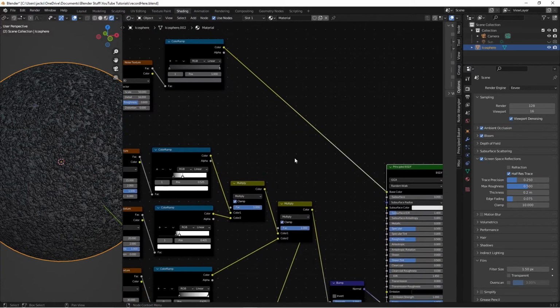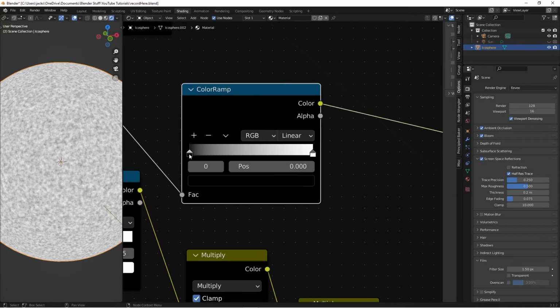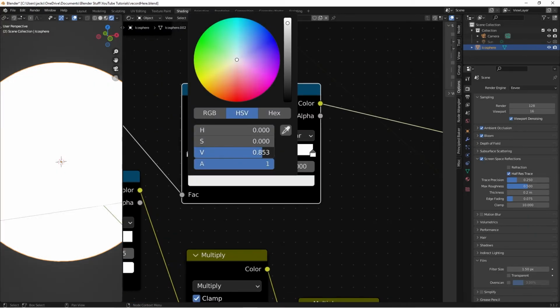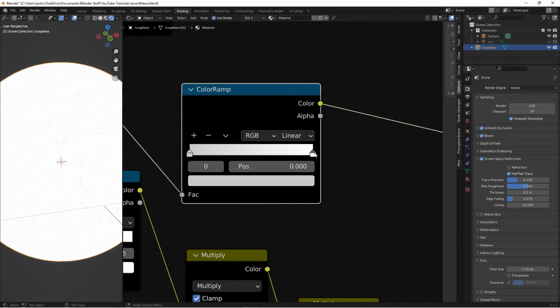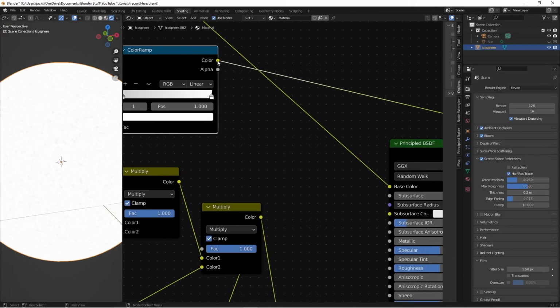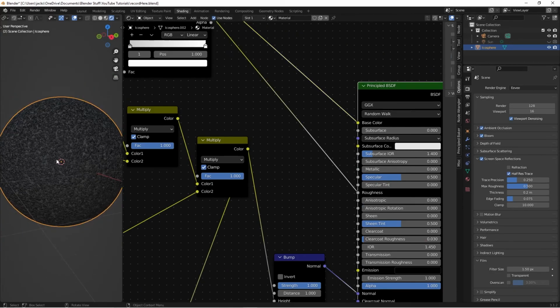Next, all we have to do is add the roughness, which is really easy. We just hit Shift-A, search for a color ramp. Right here, we're going to take this noise texture factor, plug it into here, Control-Shift and left-click to preview. And rocks are very rough, so they're never going to be 0 roughness anywhere. So we're going to move this all the way up to a 0.6. So the roughness will range between 0.6 and then all the way to a fully rough. So we'll plug that color into the roughness, preview the shader once again, and we have our finished volcanic rock material.